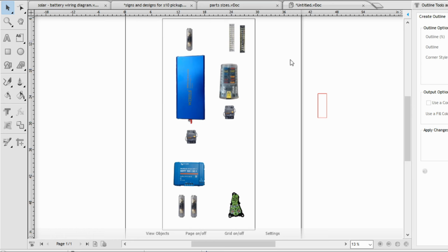So this will be coming in to here. Now a lot of these wires are going in this block. Actually, all the wires going in this block are going into the fuse block here. Fuse panel. We pull that back over here. And all my positives will come out this side. All my negatives come out on this side. Might want to move that over just a little bit.